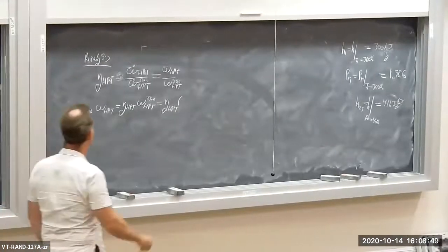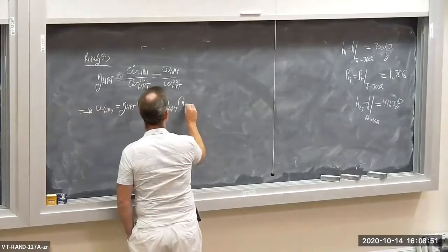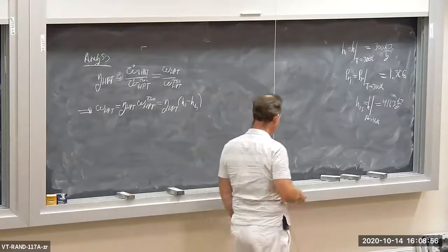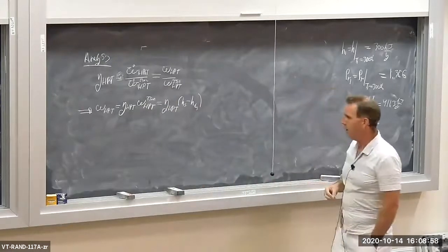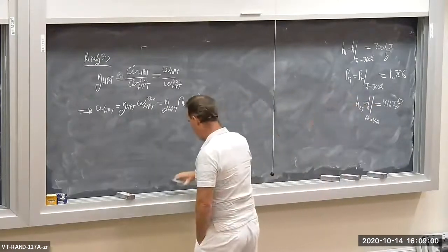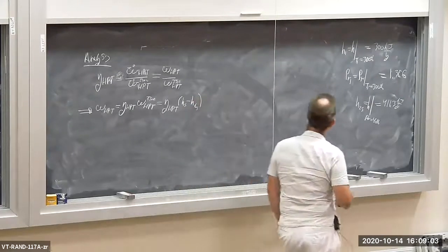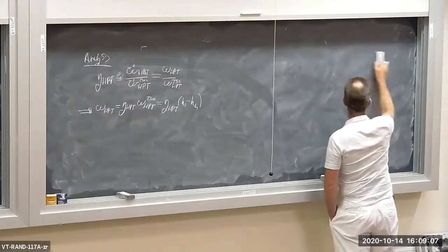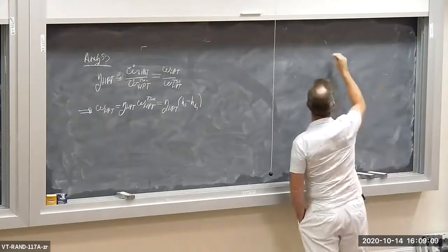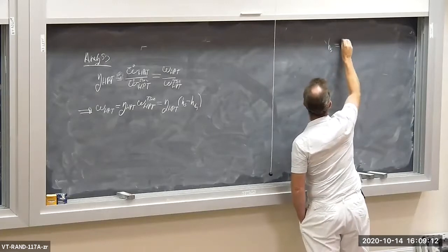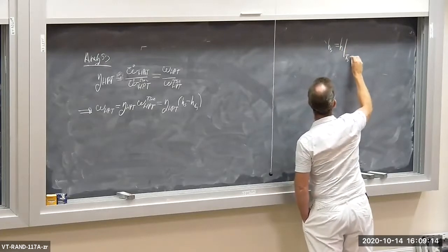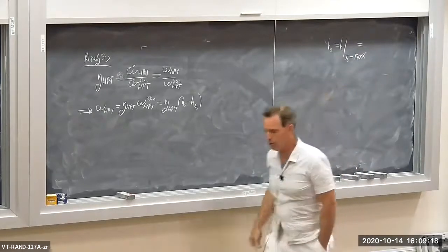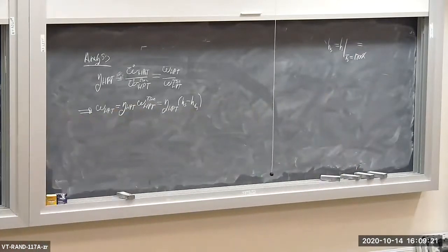So this is H5 minus H6 sub s. Okay? Now I know H5 because I know the combustor exit temperature. So H5 is equal to H evaluated at T5. What is that? 1200 degrees Kelvin? Let's have a look here. 1200 degrees Kelvin. I think it is.